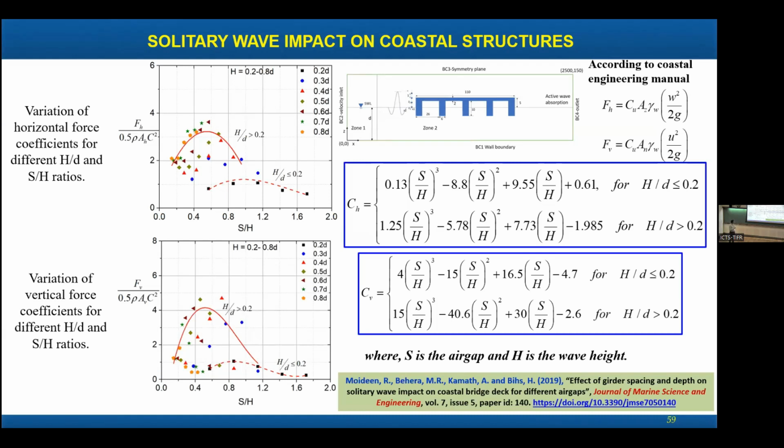So with that, we defined some kind of coefficients, horizontal force coefficient, vertical force coefficient. Once these force coefficients are obtained using wave height and air gap, S is nothing but your air gap, these two parameters, you can find out these force coefficients.